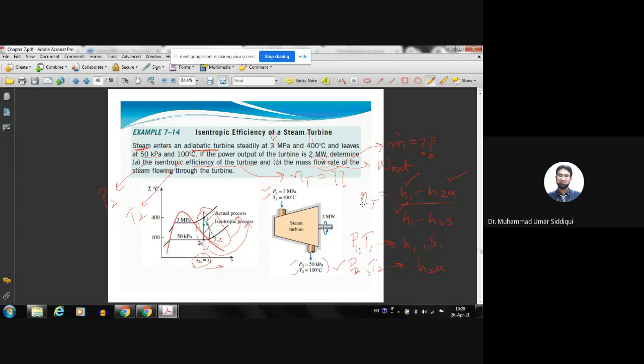When we are considering the turbine, we know that we want to move from high pressure to low pressure. Pressures are always considered the actual value. So for the case of the pressure, it is always considered that P2s is the same as P2a, which is just P2.